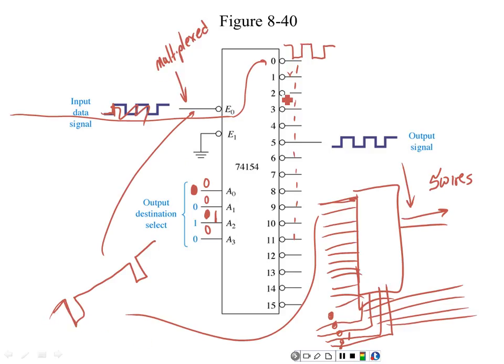And the way the decoder works is that when it's enabled, the selected output goes low because there's the circle. So output 2 would go low. Now what would output 0 be? Now it'd be 1 because it's not being selected anymore, right? Y'all understand? And then when the input goes high, this guy right here would go high. And we would come up here and generate that guy right there. So whatever's on input 2 of my multiplexer would be rerouted to output 2 on my demultiplexer.